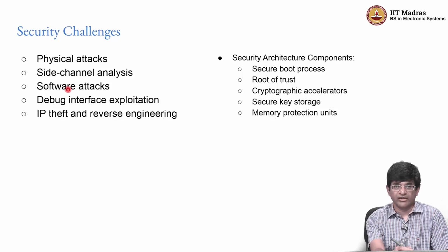However, this is also a very difficult task in general, because there are numerous different kinds of attacks that can be executed against hardware or software, which includes physical attacks, where somebody gets hold of a phone, let's say, and by opening it up, you can almost go down to the point where you solder wires onto the JTAG access ports and directly get access to the internals of the chip. At that point, it is extremely hard to prevent the leakage of information. But there are ways even around that, to ensure that even if somebody has that kind of physical access, they still cannot extract information from your system.